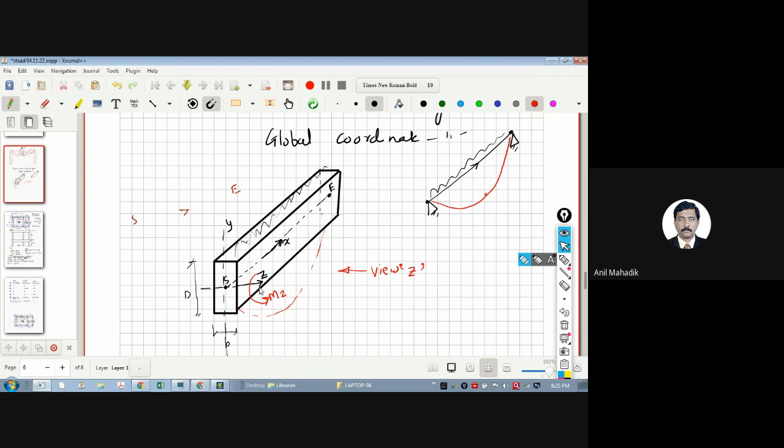About this z axis. That's why this is your Mz. Getting all of you? If the beam bends in plan, suppose it is bending in plan like this, seen from above, I can see it in this view. What is this direction? Y. And where you see the bending, if you look from the Y direction, then you see this bending in plan. That's why it is called My. So the bending in plan is My, bending in front elevation is Mz.